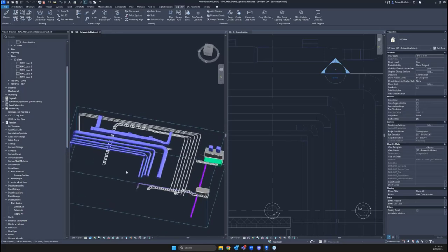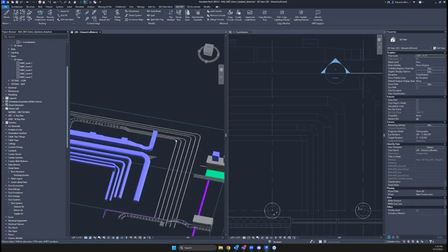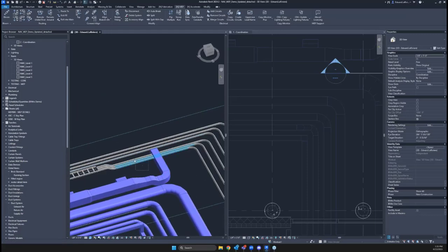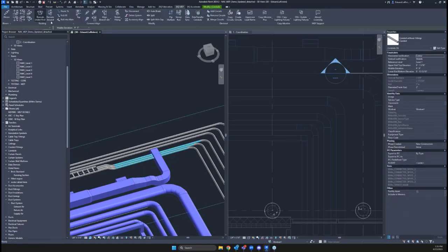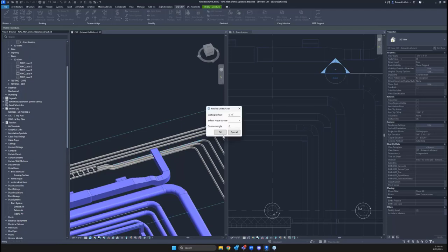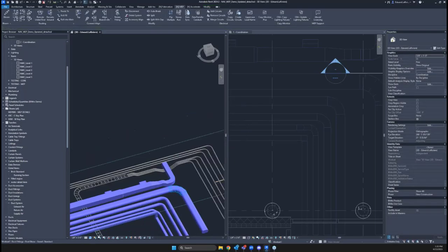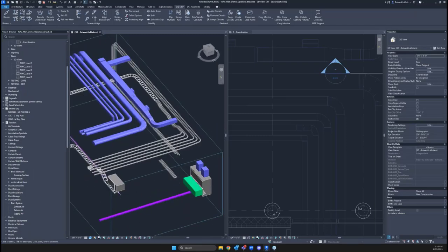I want to do one last quick one on some conduit. We'll do it again on some ductwork, but I'd like to introduce the reroute under over command. This is one of my favorite modeling commands. Jumping over this way, it's a really quick way to grab a rack of elements. Choose your left side and right side cut, a vertical offset, maybe -1 foot. And let's do a 30-degree bend here. Incredibly quick way to start clearing clashes.